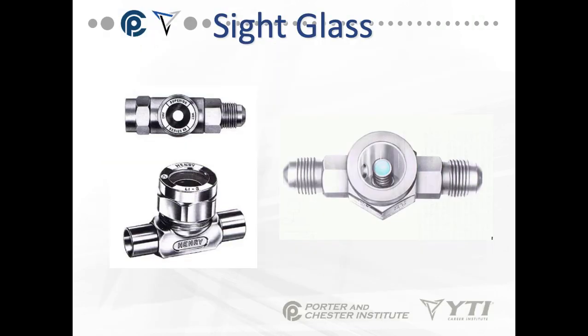Sometimes we have a sight glass. We'll talk more about this when we talk about refrigerant pressures and charging refrigerants. Primary purpose of a sight glass is to tell you if there is moisture in the refrigeration system. They all have a moisture indicator that either tells you if there's moisture or if there's no moisture.